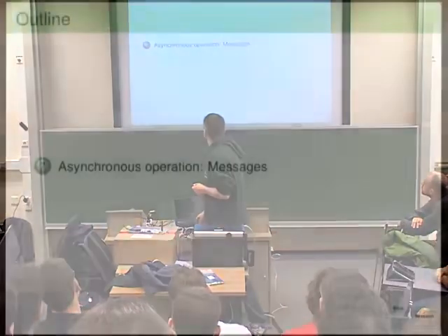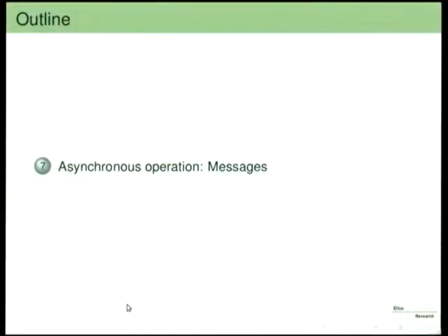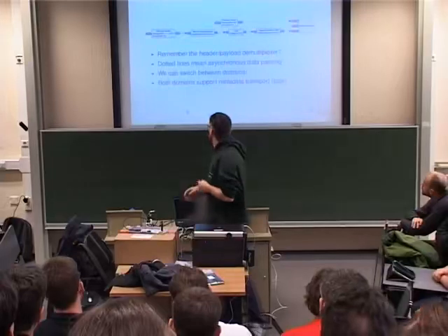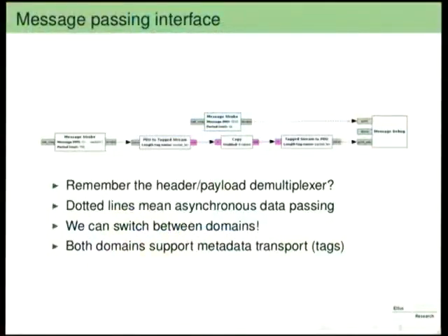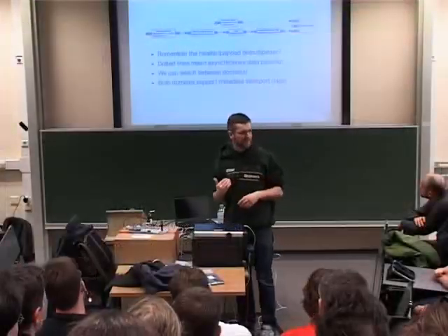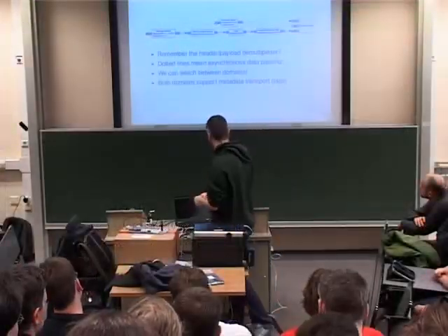Now, what we need here are what we call messages or asynchronous operations in GNU Radio. So you remember the dotted line in the header payload demultiplexer? This actually already uses this feature for a different reason, but it's really designed to be able to run your own MAC.